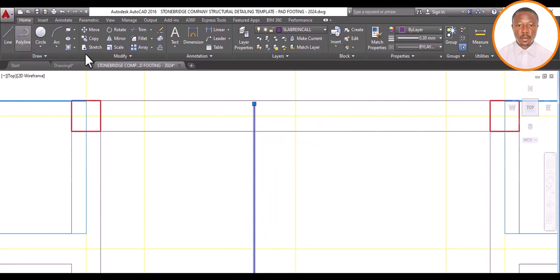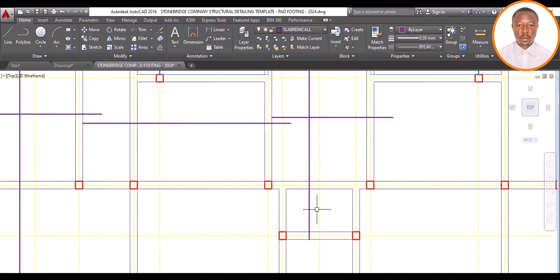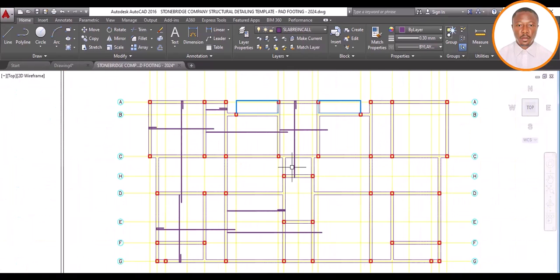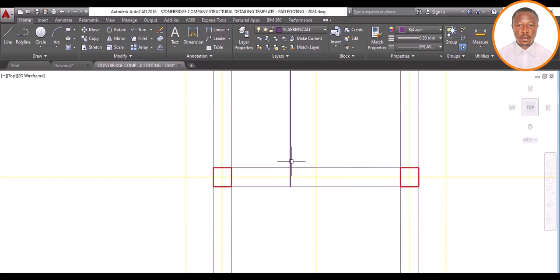Enter. Then pick my line. Then at this point, I have my reinforcement thickness 600. Then I have my return bar as what? 600. Good. So that holds that beam back. And also, because this place is a void, I also have to do the same thing here. And take my 25, yes. Then pick my line and come to this point and take my reinforcement thickness, which is 100. You remember how we got the 100.